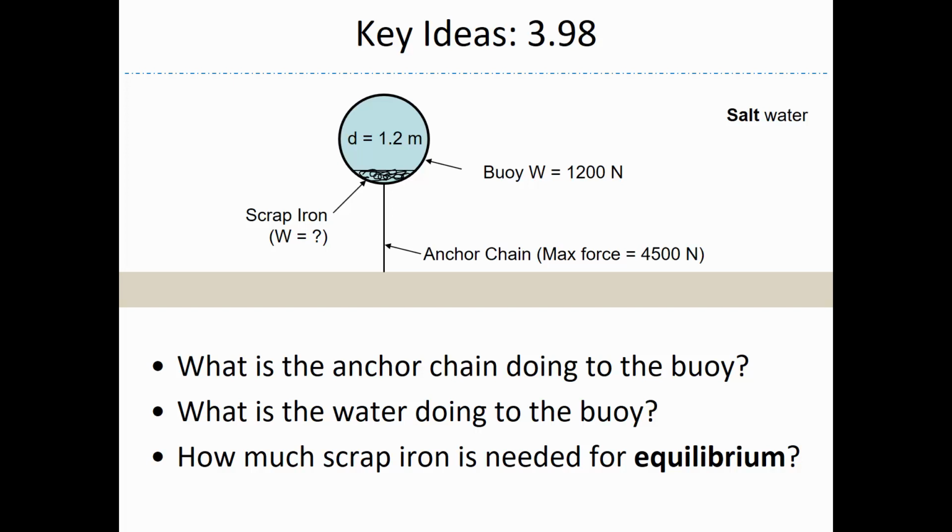It's a submerged, like a submerged buoy. And they don't give you a picture in that problem, and I thought that maybe providing a graphic would help to clarify. First of all, it's submerged in salt water. And so you'll need to look up the unit weight for salt water, and it has that in the back of the book. The density and the unit weight's a little bit higher.